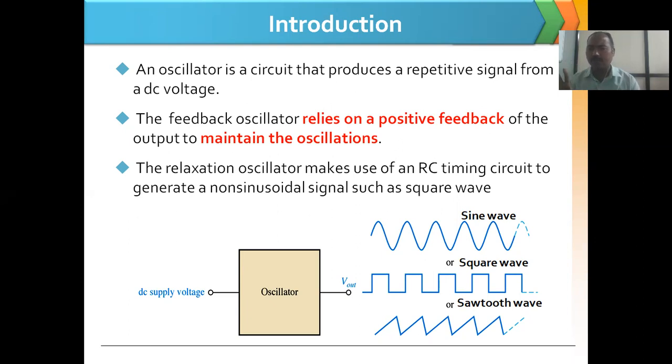Due to negative feedback, there is a reduction in the gain of the amplifier, but it is stabilized, right? So for gain stabilization in an amplifier, we use negative feedback. And for the generation of a sine wave, in an oscillator, we use positive feedback. Two points according to what I am explaining are important: positive feedback is in an oscillator, negative feedback is in an amplifier. Okay.